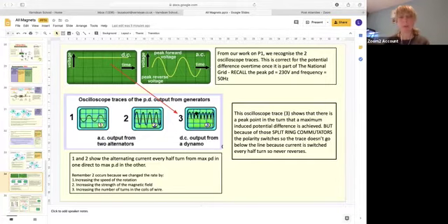We've got a peak potential difference here, but because it's doing a rotation, it's not going to stay at peak the whole time. So it will drop back down, but it will never reverse. It never goes below the line. So a DC output from a dynamo gets this M shape that never goes below the line, but it fluctuates because there is an optimum point in the turn of the coil where everything is perfectly matched up with the field lines going through.